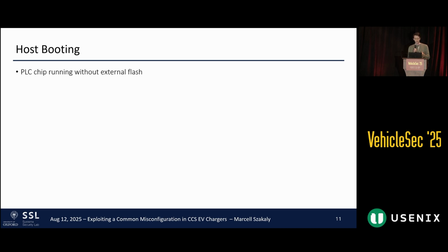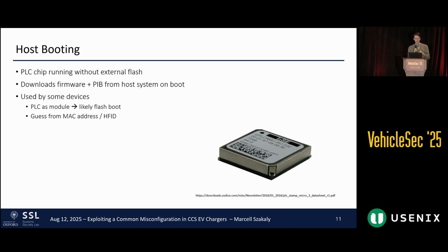Quickly, I would also like to mention host booting. There is an option in the standard where the PLC chip can run without having any flash chip. This means that it doesn't have its own firmware and it doesn't have a persistent place to store its configuration. Instead, it downloads it every time from the host system as it boots up. This is used by some devices. If you buy PLC as a module that you can see here, it's likely going to have an integrated flash chip to be a nice self-contained system.